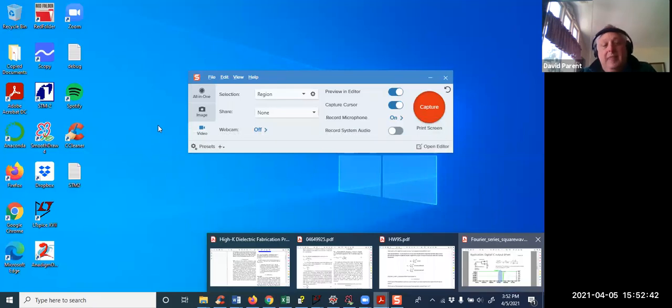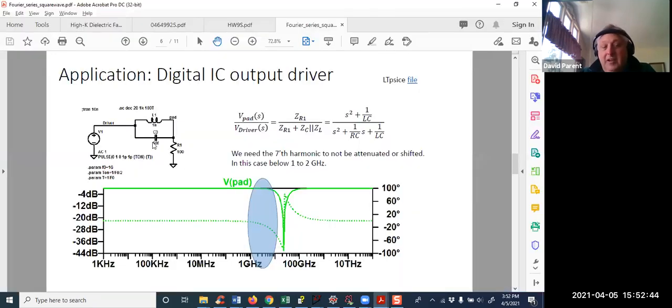All right, but so here's the thing, this makes a filter, right? So this is the outside, these are the wire, represents the wire to get to the pad on the inside. And so we find the transfer function, right? I have ZR1 and then ZC is in parallel with ZL, right?